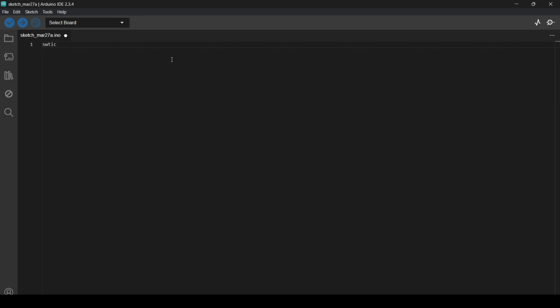So let's say you want something like switch on the lights, for example. Pretty straightforward. A human can understand it. Now, how can you get a computer to do it? The code you would write in our specific example would be digitalWrite, effectively giving instructions to write to a specific pin on your microcontroller board. So in this case, an LED pin with the light on. And you set it to HIGH, which is to switch it on. And you have the brackets in, because that's expected syntax.